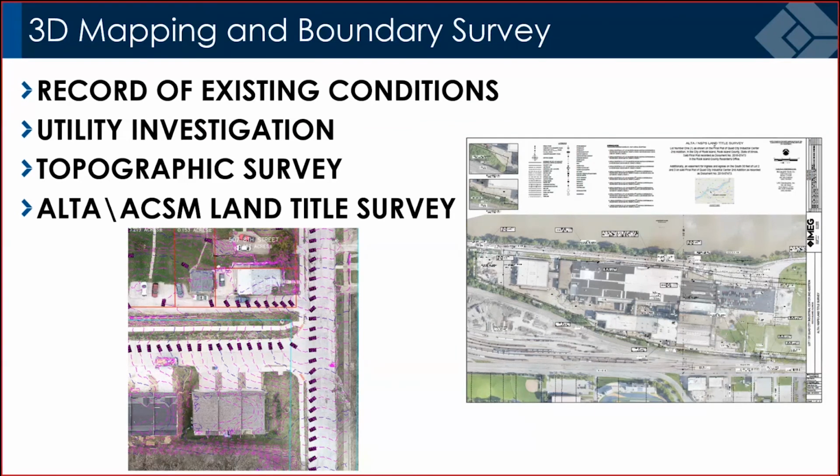3D mapping, of course, with topographic surveys, large open spaces. So areas where before we would hop on a 4-wheeler and GPS it, we may be able to get it with the drone. Boundary surveys, we've been helping out there too, as well as with regards to ALTA and land title surveys. So again, sometimes the actual imagery may tell more of a story than actual line work on paper.